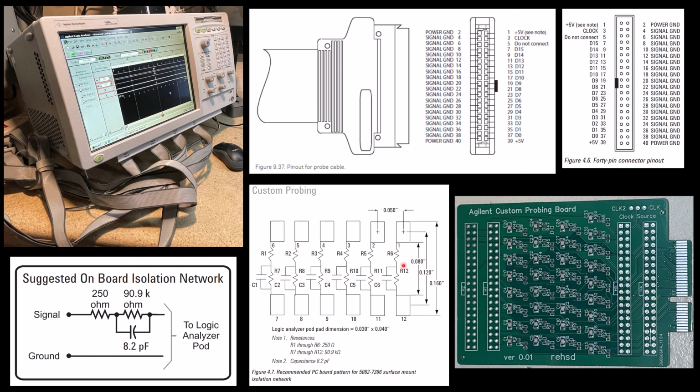What you're going to see on the left, which will be the top when I actually click it into the board, each of these pin headers I can connect directly to one of these cables. So I can come out of a pod connector in the back of the chassis. It comes out as 2 of these, which will plug into these 2 on this card. And this will just click right into my 386. And that will give me access to grab all the signals out of that PCI Express connector, which is 32 signals.